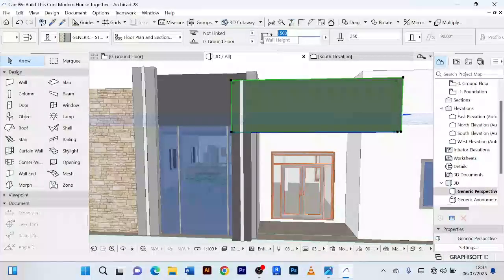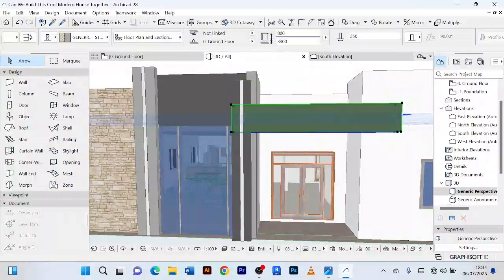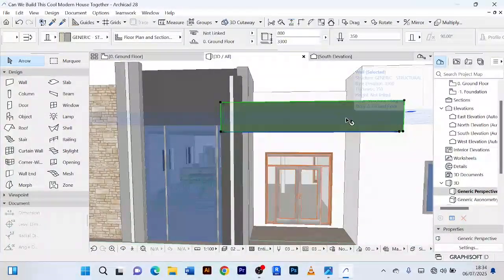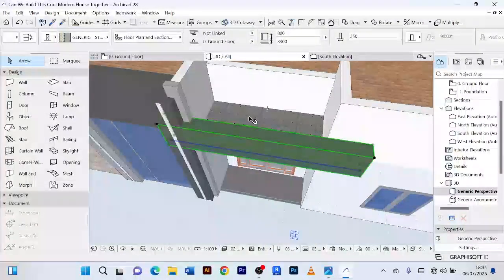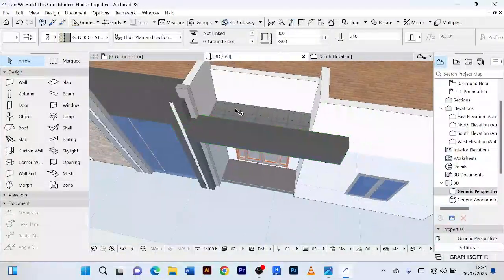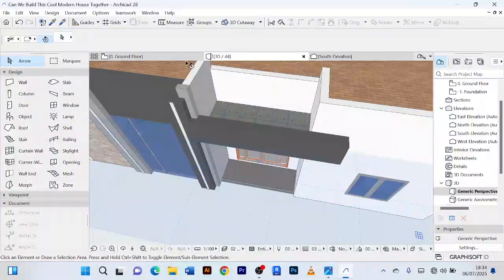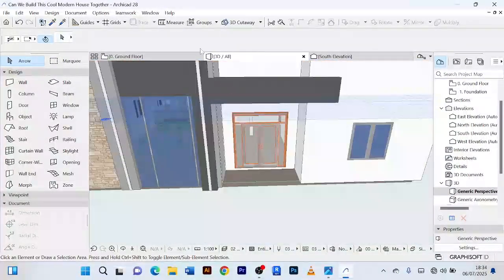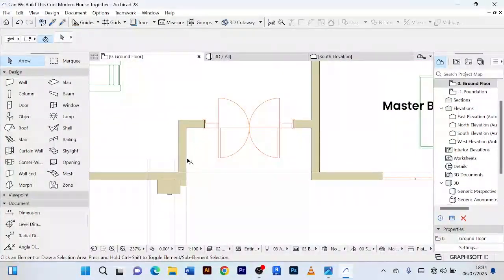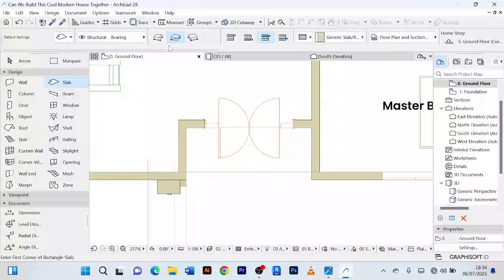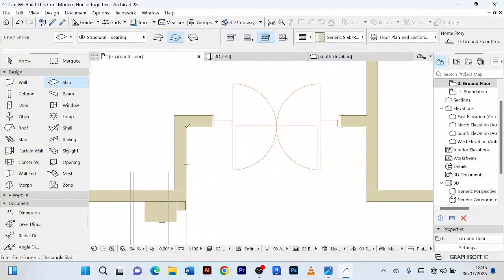So I'm going to change the wall height from 15 to 800, just like that. Then we shall have something like this. Then I also want to create another floor to cover up this part so that we don't have this opening or this gap here. I'll come to the ground floor. This one I'll do from the ground floor. We shall go to the ground floor. Just here, I'll create a slab around this part. So I'll come to the slab tool, then I can just start drawing. Actually, I'll just draw from here up to here.